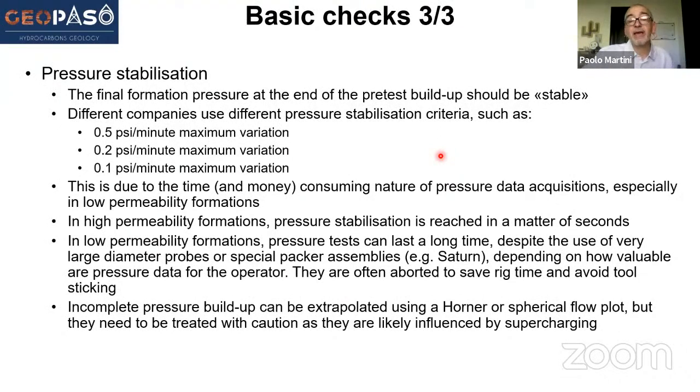It depends. And this is due to the fact that pressure data acquisitions take time, and time is precious, especially when you are offshore and you're paying hundreds of thousands of dollars for each day that you spend operating the well and drilling the well. So in high permeability formations, pressure stabilization is normally reached in a matter of seconds. In low permeability, then it's a different story. It can take a very long time.